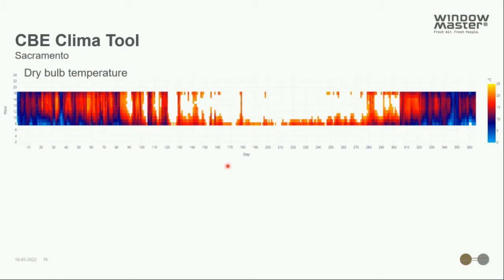Now, the design that we have made before is based on a temperature difference of 5.4 degrees Fahrenheit, or 3 Kelvin. That was the design criterion that I set. So we know that when the temperature difference is above this criterion, our design that we have calculated will comply with the requirements, and when it's below this temperature difference, it will not comply.